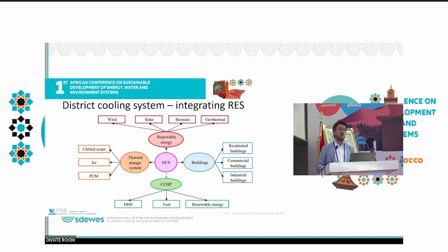So another important issue, as I mentioned, fourth-generation district cooling systems are all about decarbonization and all about integration with electricity and district heating. So the key component here is integrating renewables into those systems. We can look at it from two points of view: from the thermal point of view, or from the electricity point of view. From the thermal point of view, there are numerous renewable energy sources that can be integrated into the system. We usually need some kind of absorption chiller technology in order to do that. So for instance, if we talk about geothermal, we can also utilize waste heat from geothermal power plants if there's availability. We can also consider groundwater source heat pumps as one of the technologies. When it comes to biomass, solar thermal, waste heat, we usually utilize it through different kinds of absorption chiller technologies.